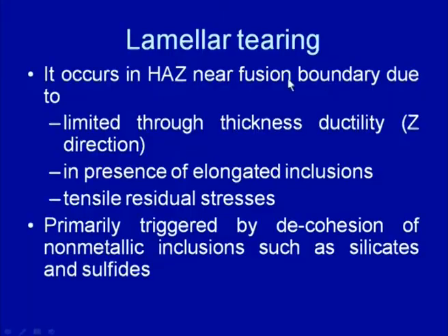So, when these laminates are present and welding is done, tensile residual stresses are set up during the welding, especially in the direction perpendicular to the direction of thickness. The decohesion of these lamellars or inclusions leads to the development of cracks, especially in the regions close to the fusion boundary or below the weld zone. Since it is mainly encountered in the heat affected zone, it is a form of HAZ cracking,